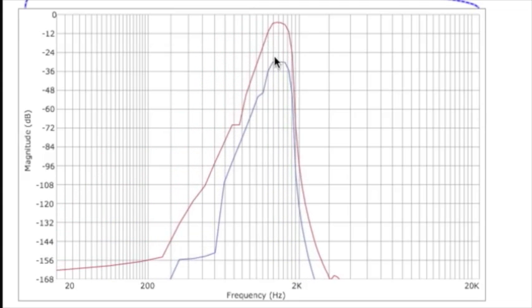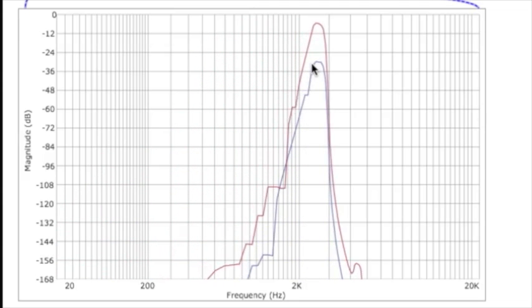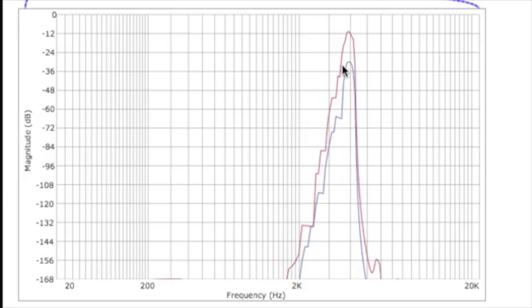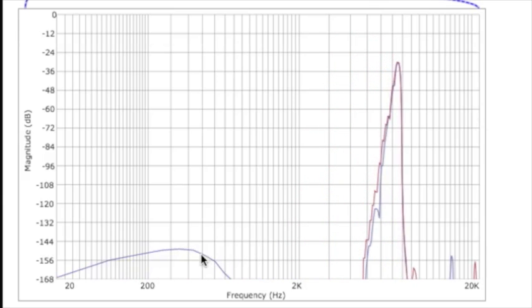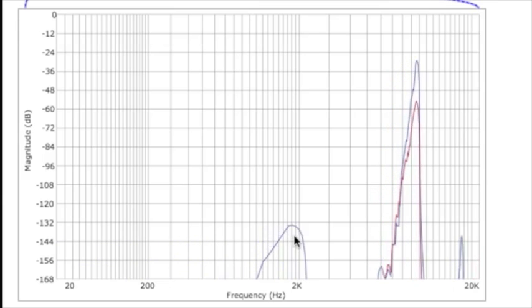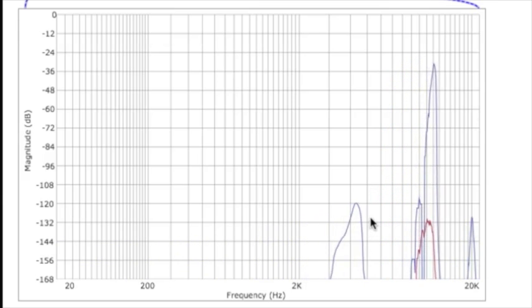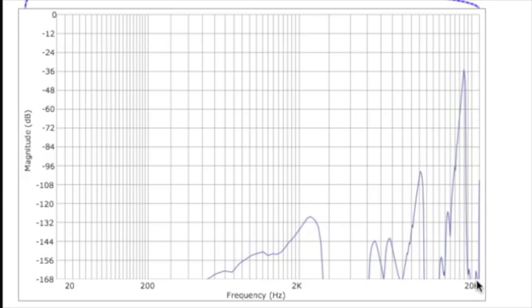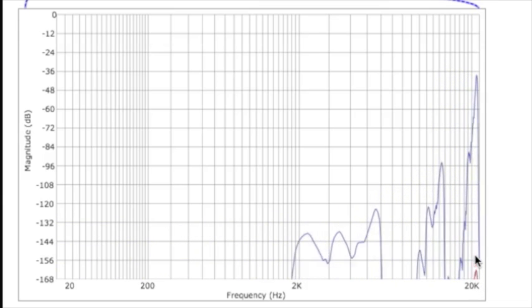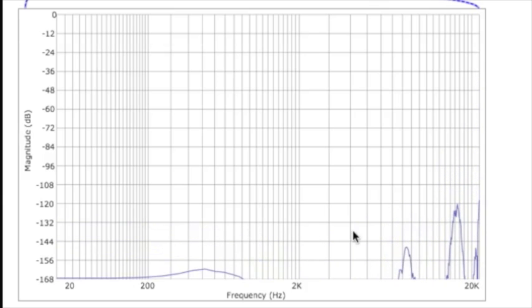So that frequency is located right here at this main lobe. The blue is the groove as it's always existed. The red uses the new resampling attribute. We can start to see down here that there is some significant noise as frequencies are aliased back into the spectrum that shouldn't be there. As we get to 20,000 Hertz, the red goes away, but instead we have all kinds of noise coming out of the original. So this represents a dramatic improvement in the sound quality that we can achieve in Max 6.